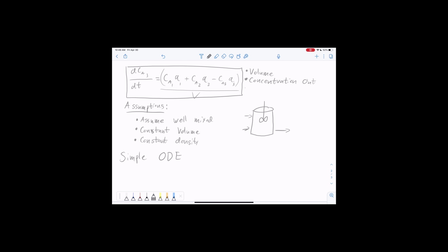So a mass balance or species balance is all that we really have going on. If we were to control this system, we have 2 inputs and 1 output. The main thing we would probably control is one or both of the inlet values, and probably the flow rate of one of those or both streams. Manipulated values could be, for example, how well it's mixed, or it could be the concentration. Outputs would be the volume right here and the concentration here. The volume inside the tank and the concentration out. These would be states, since we're not actually controlling it in this problem, but they could be controlled variables if we did adjust something to control those.